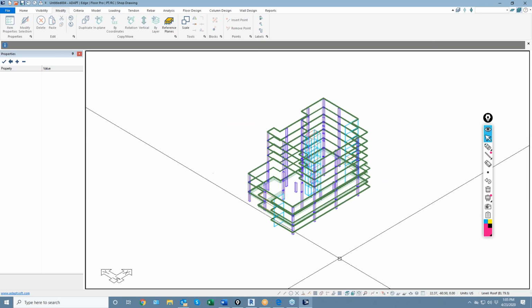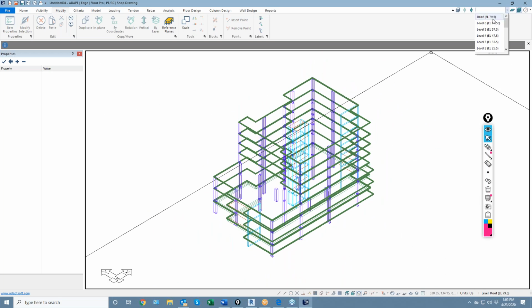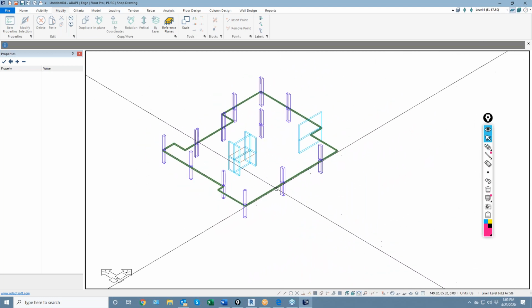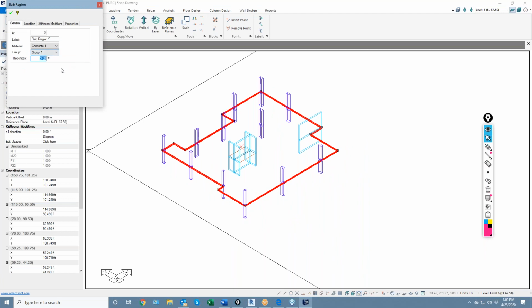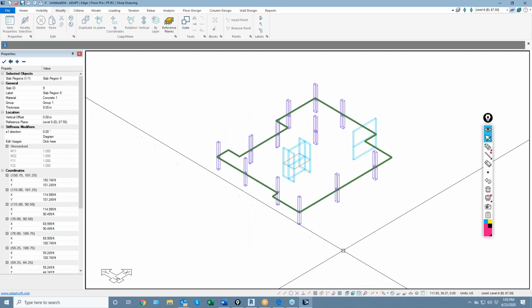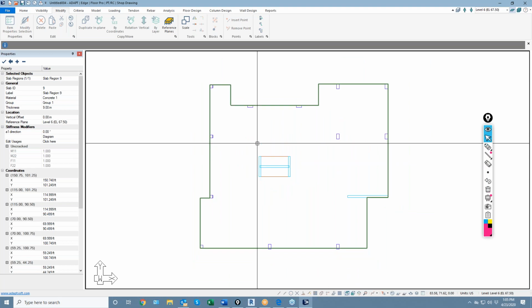So right now you see we have a multi-story model. I'll go over here and go up to the 6th level, single level, and we're going to primarily be working on this level. Now this slab is a 9-inch slab. I'm actually going to change it to 8. I think it was sized originally for RC. We're going to change that to an 8-inch slab. And we're going to jump right into loading the model with some gravity load and then getting into design strip layout and tendon layout.